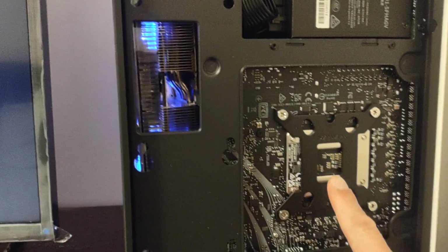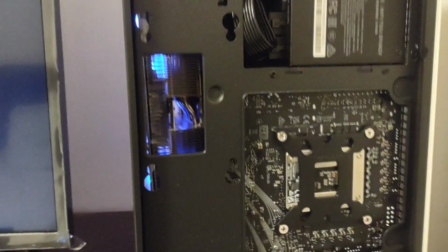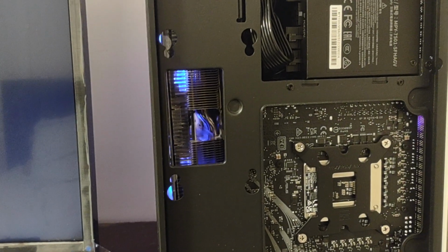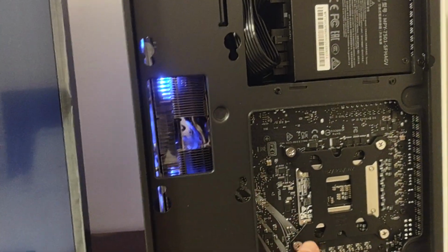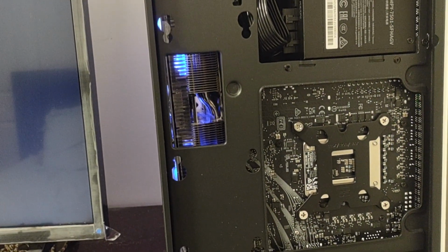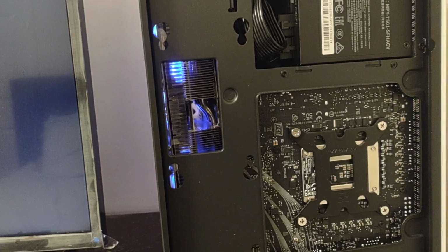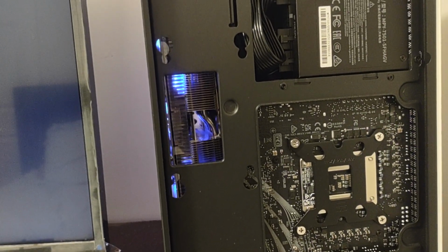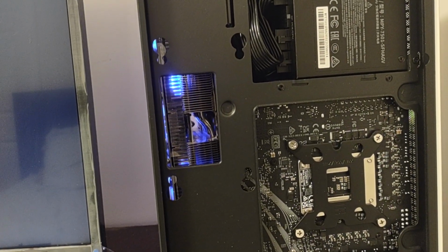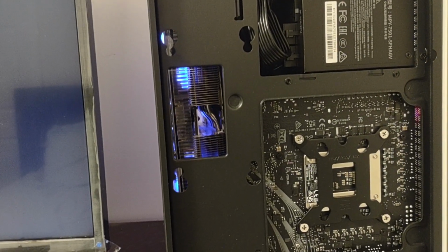Another possibility, believe it or not, is your motherboard. Like, how can it be your motherboard? Well, a lot of motherboards like the X570 have a mini fan built in. This Z690 actually has a fan built inside the motherboard for the VRM, and that only kicks up when needed. You can control that in the BIOS, but sometimes that could also be the problem. That one little fan within the motherboard can cause the problem.